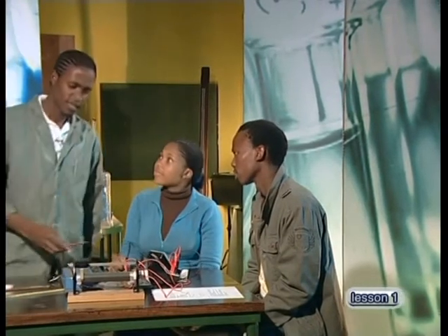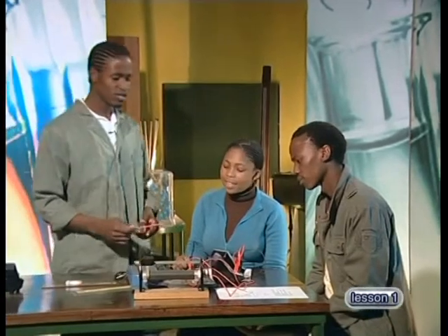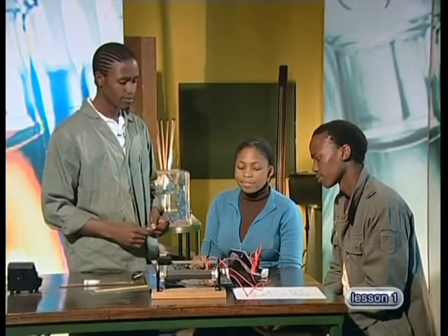Okay, I think we've got it. Excuse me, sir. Can you please come check our circuit? That all looks right. I'm glad to see that you have both the meters connected correctly. If you don't remember to follow the directions of your current from positive to negative, you might destroy them. Now let's check your rheostat settings.